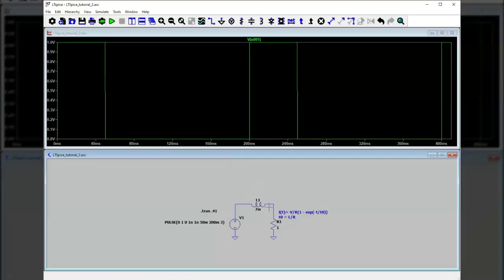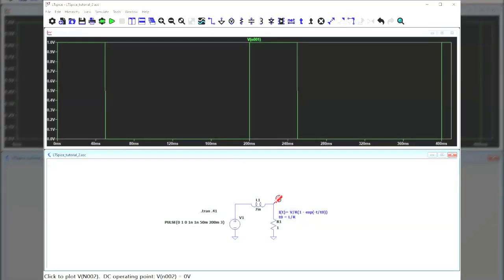Now what you would more likely care about is what the voltage here looks like, and we see what would look identical to the RC, the voltage on the capacitor. This is actually kind of a current waveform, but it turns out to be a voltage waveform also because this is a 1 ohm resistor and we're looking at the voltage across the resistor.